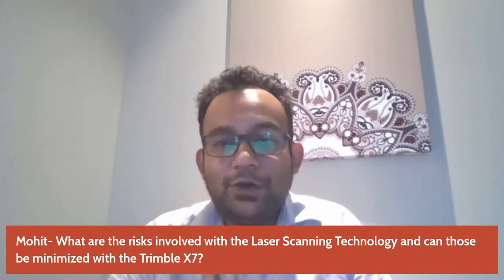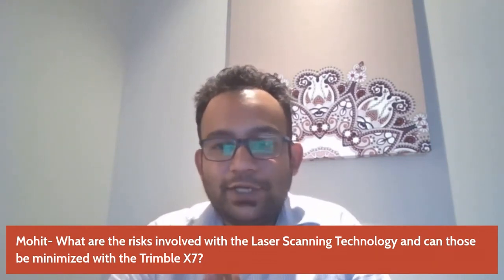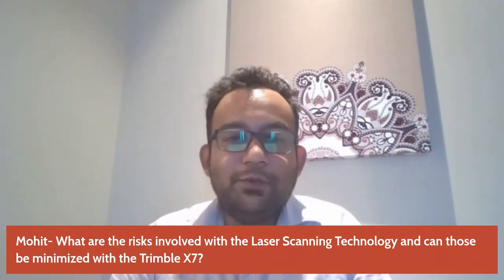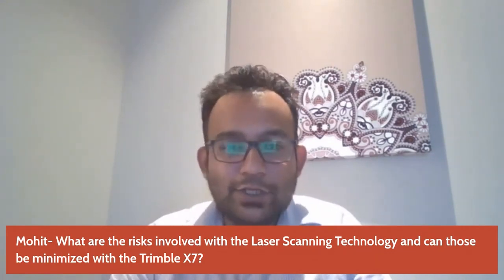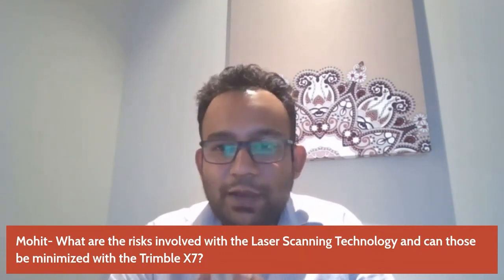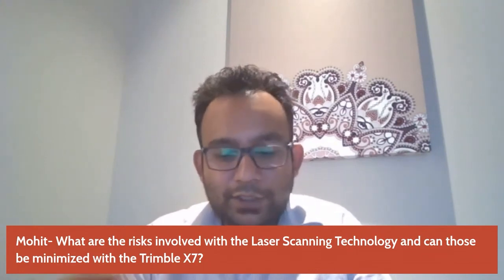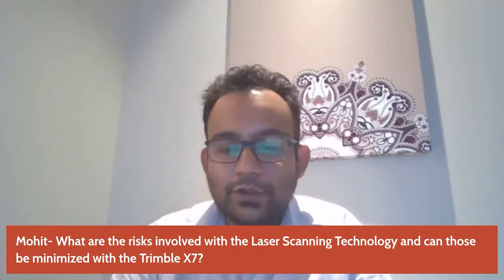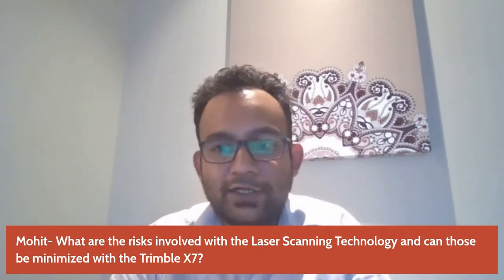And when you are talking of a precision level of surveying, wherein a lot of details matter more, then all your risk would be minimized with using the laser scanning technology itself. And Trimble X7 will allow you to capture your data a lot faster, because a lot of the part which you'd traditionally do in your office, certain basic measurements, stitching all your scans together, georeferencing all your scans together, will be done on the field itself.